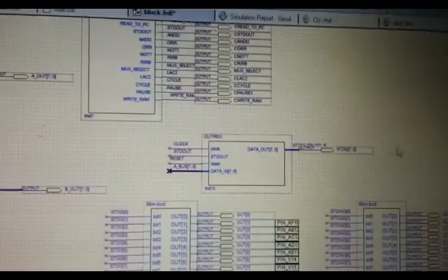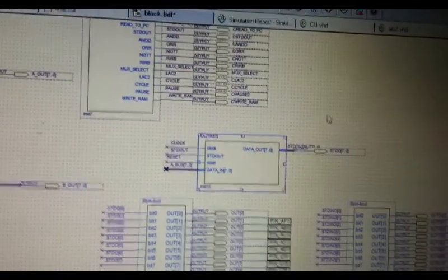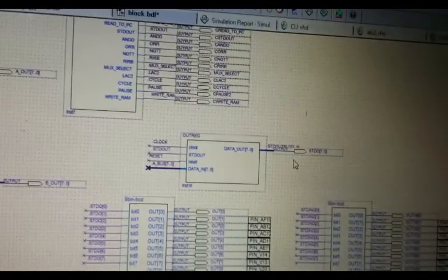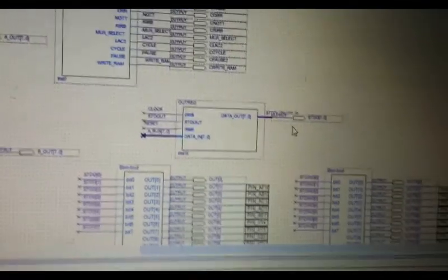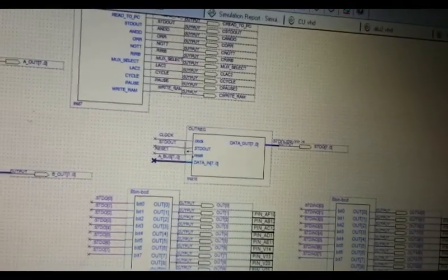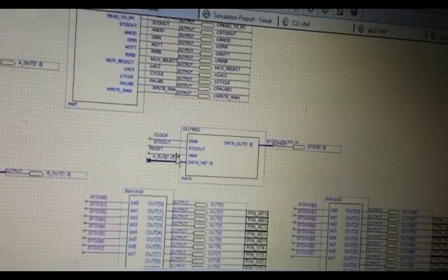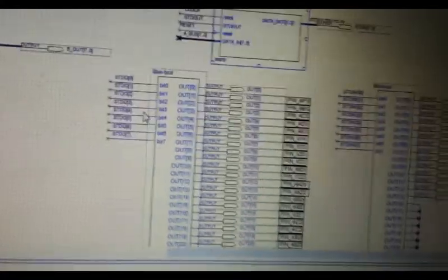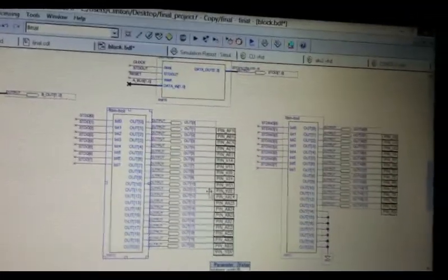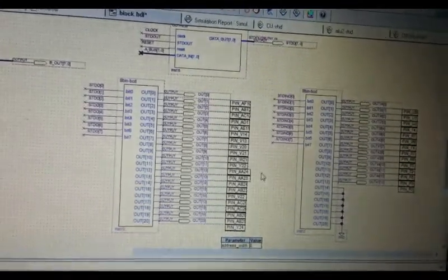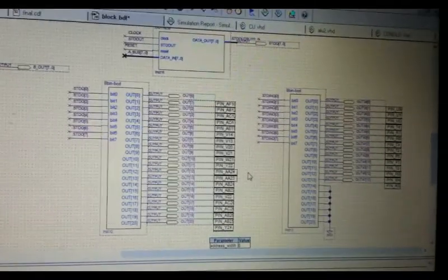Right here is a register, and all the register contains is whatever is on the A bus when we need to output to the LEDs. So just really simple, just an assert signal for STD out, reset, clock, and also the data, which comes from the A bus. And these two over here are just 8-bit signals to the LED outputs.